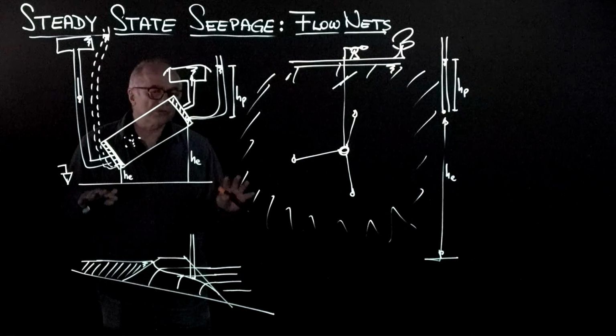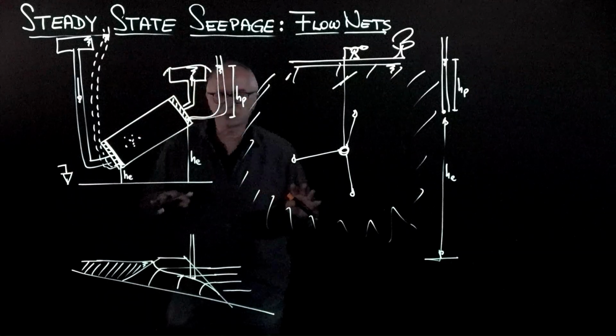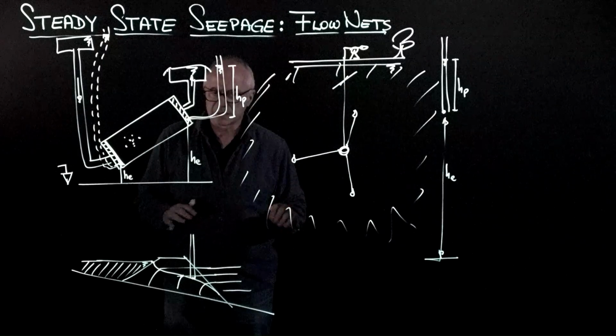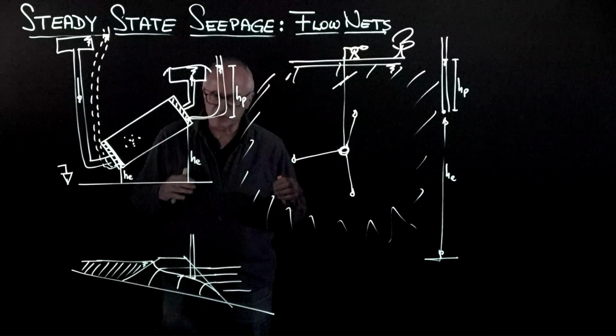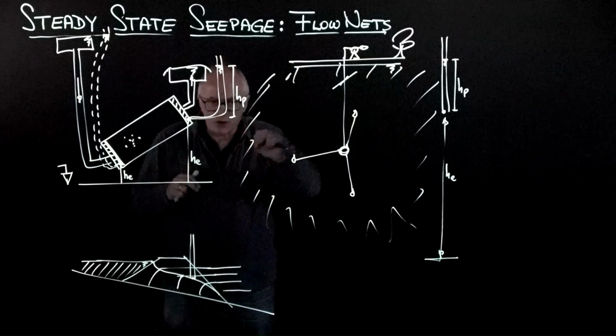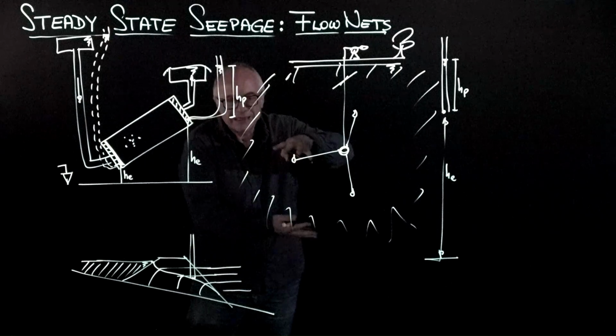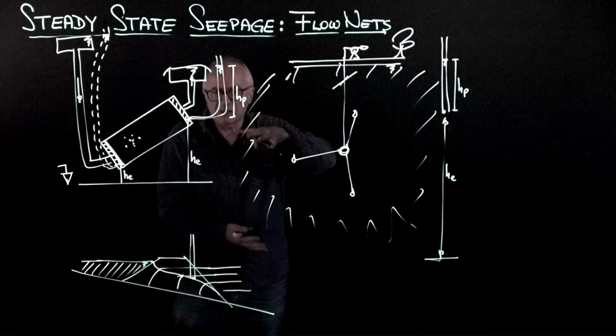we are going to solve Laplace's equation by first of all identifying the boundary conditions. In the simplest of all cases, we would like to identify the shortest flow line and the longest flow line, and all the flow will be channeled in between these two.